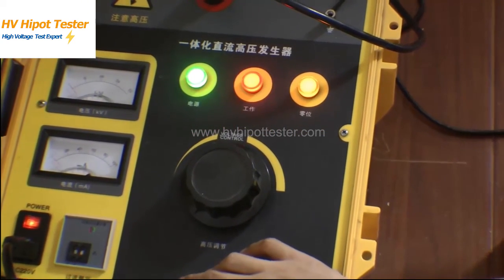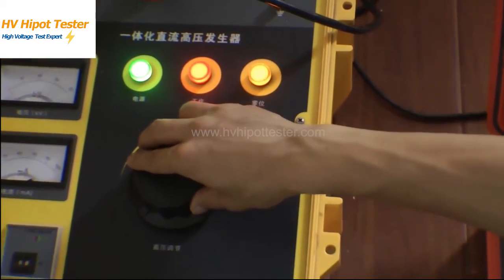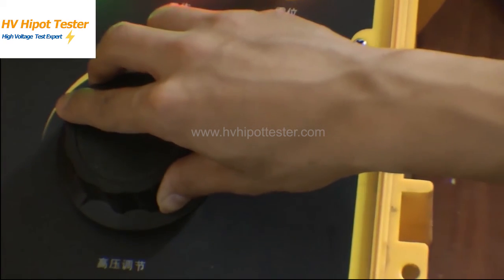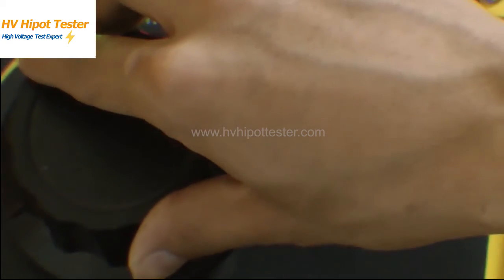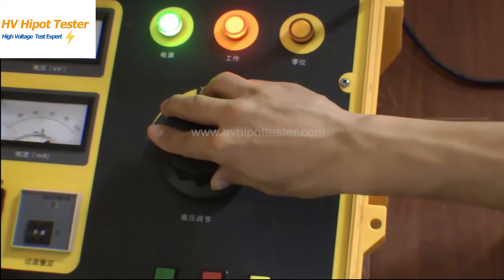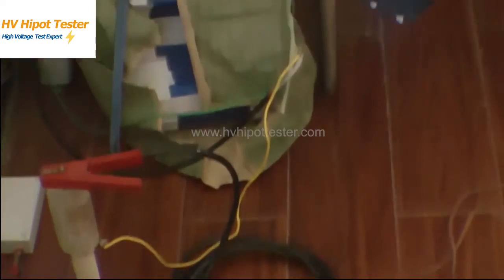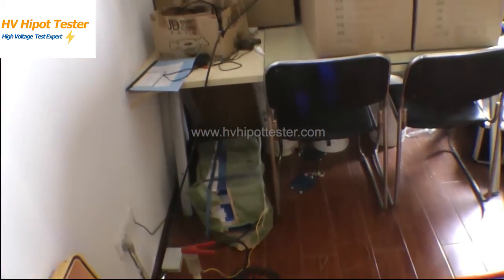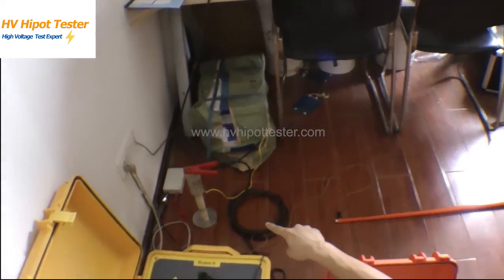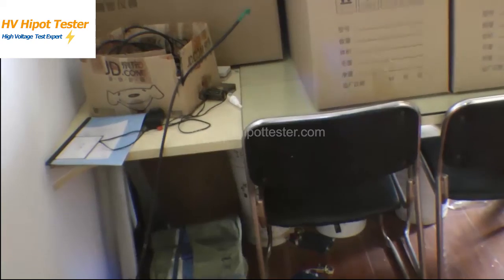Please note the HV generator should be grounded to avoid it from burning. To start, the work light is on. Adjust the voltage by the knob slowly, until you hear this kind of sound. Each time the sphere gap is discharging and the cable fault point is discharging at the same time. At that time, we go to the corresponding place and use the shock sensor to listen to the sound from the ground.